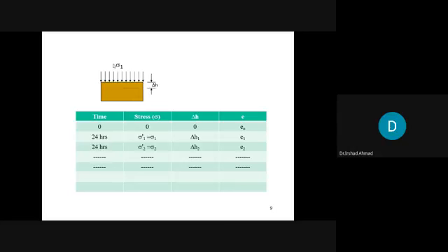As the water goes out of the soil specimen, it would be accompanied by corresponding compression of the soil specimen, right? The compression of the soil specimen would start, and after 24 hours, it would be complete. It would almost no more get compressed.